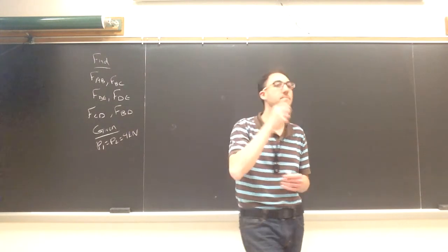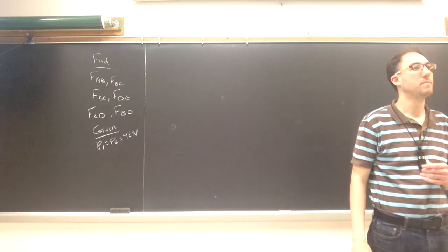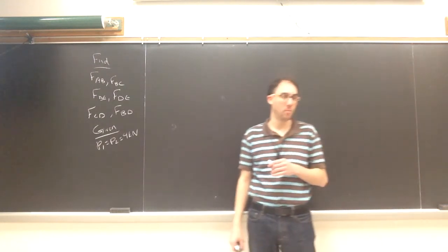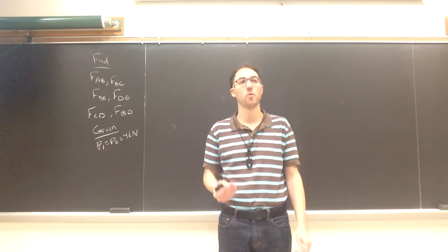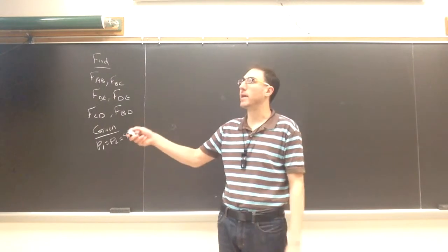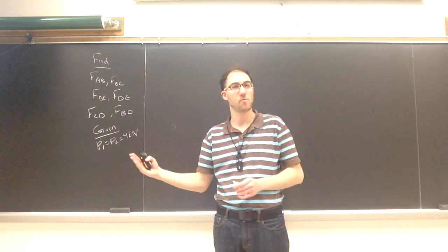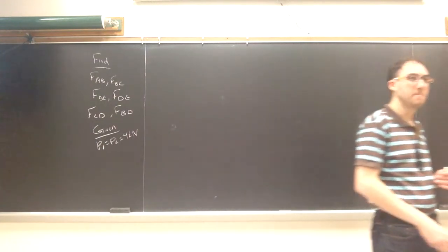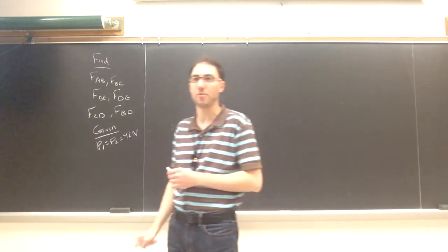So if it's a zero force, does that mean we don't have to use a free body diagram for it? It means that in any free body diagram where it would appear, you would not have to include it because you know the force is 0. So it could make it look like there are fewer members attached to a pin, and it's less to write and fewer things to solve for. Right, other questions on zero force members? We'll see more examples as we go through.